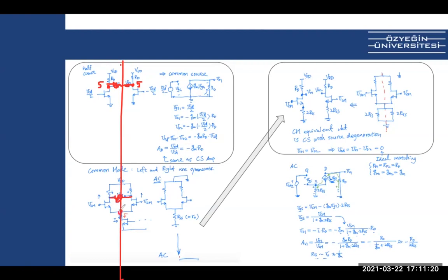This kind of becomes open too, but there is this resistance here, which we want to carry to these 2 points, so we want to make the circuit equivalent to it. But this one, we cannot really do. So in this case, we have a resistor with an open node, which doesn't really make any difference because there is not really any current connected there, any ground or any node connected there.